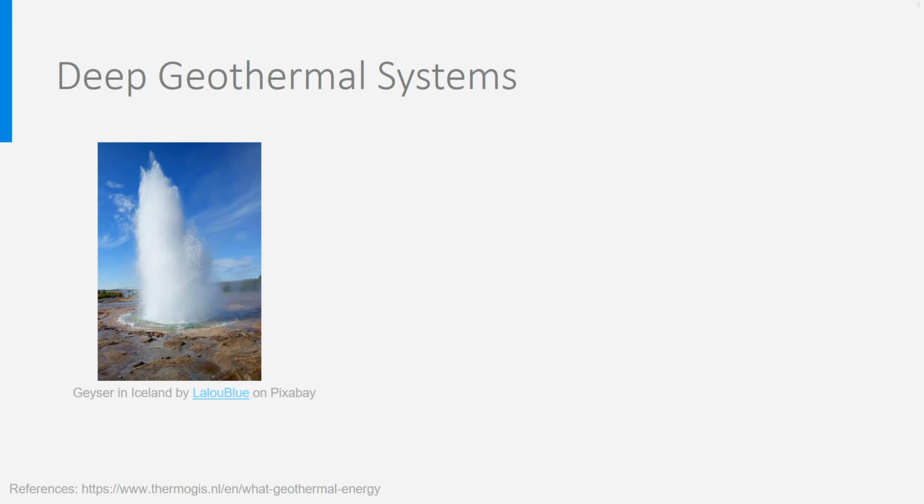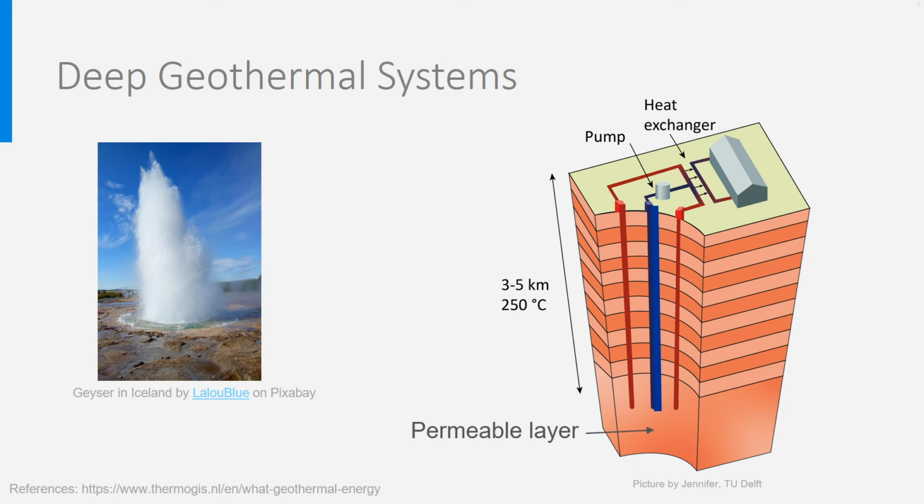In the picture left, you see such a geothermal plant with 2 wells to extract warm water and 1 to reinject it. One point of attention for the future is that a cold bubble is created around the injection pipe, which could disperse towards the warm well. It is believed that after 20 to 50 years, such a geothermal system would have to stop because of this. However, there may also be possibilities of regenerating the layer by boring a new well a bit further. In the heat exchanger above the ground, the hot groundwater or steam gives its heat to a hot water distribution pipe connected to district heating.